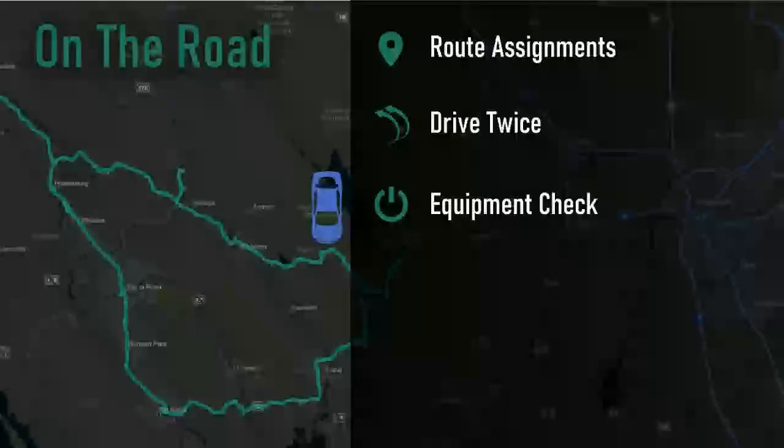Equipment check is always important. Like I said, we found the weak link is mainly the connection points. We want to make sure that all the equipment is calibrated, it is leveled, and it is ready to work for you, and that we have a strong GPS signal. So we usually have redundant equipment in the car available, a second kit, so to speak, able to collect the data, do a hot swap, and carry on driving, because you never know what can happen on the road.